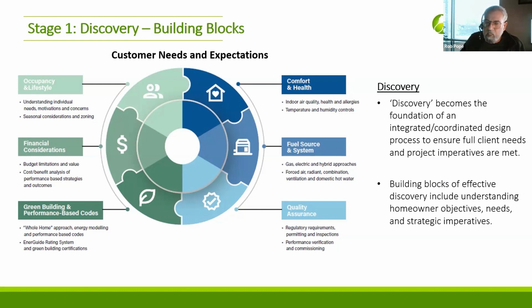So the aesthetic is a missed opportunity. It's also things like, there's an awful lot of situations where simple things like joist directions can change because the span is fine either way, but the difference it makes to hiding your HVAC is profound, right? A simple little change could really make a big difference. That's a missed opportunity if you don't work that out ahead of time.